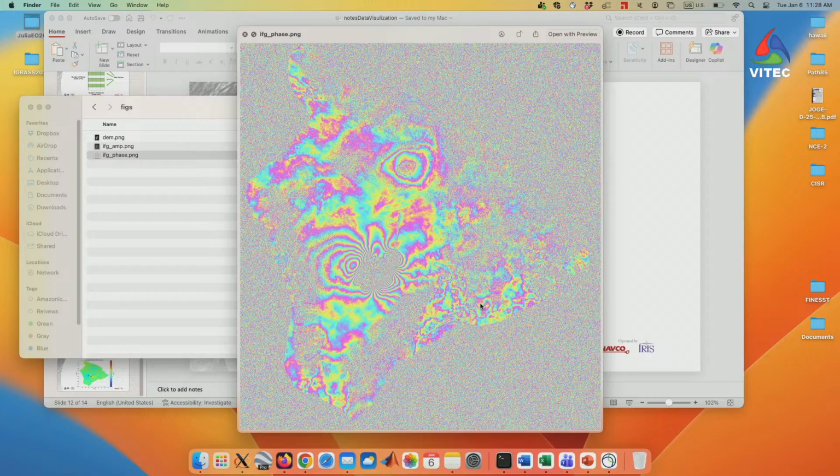It doesn't really have a clear correlation with the topography because this is a beach area, pretty flat, right? And these are the things I have to deal with 100% of the time because there's no prediction model that can capture this kind of signature. The primary way to mitigate this is to have many acquisitions, and their noise on different days is different. If you have multiple interferograms from the same day, that noise is the same. So based on a lot of these ideas, you could try to reduce the contribution of these in your final map. That's one primary reason we need thousands of interferograms, to mostly get rid of that.